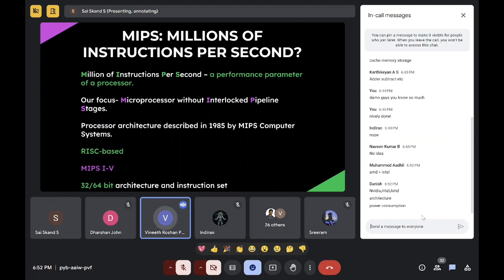So essentially what Intel and AMD have done is they're using CISC, or complex instruction set architecture. Commonly these are x86 processors. So there are two main differences between that and a reduced instruction set processor. In reduced instruction set, all of the instructions have a standard size, so it makes it much easier to go through the pipeline stages of fetch, decode and execute. We'll get into pipelines a few sessions in, but it makes it easier for the CPU to understand what the instruction is doing and do it correctly. Whereas in CISC, all the instructions have different lengths.